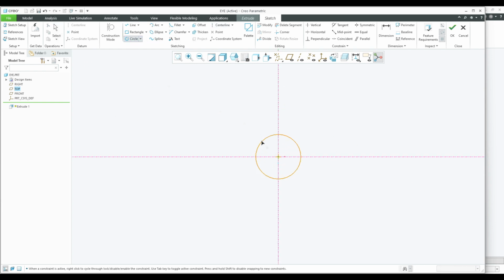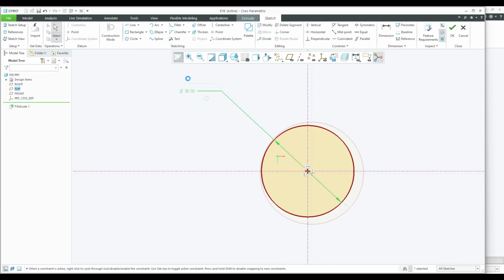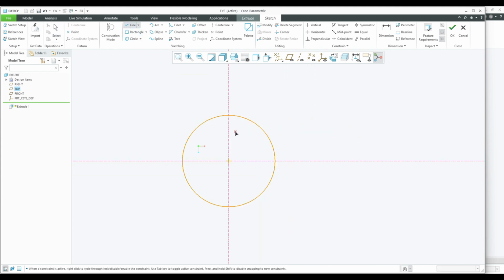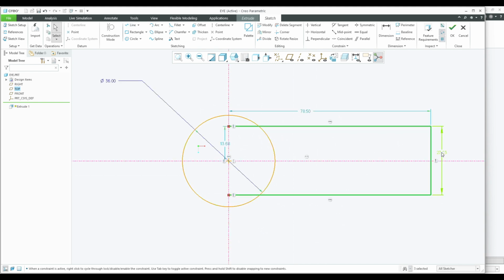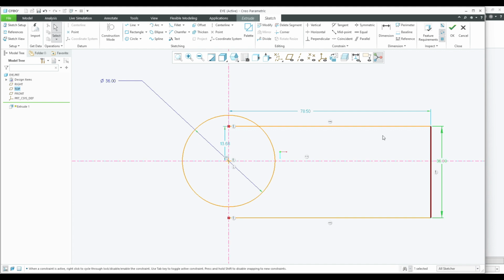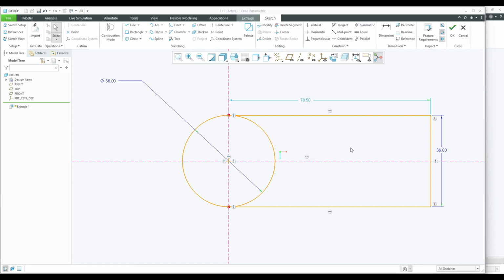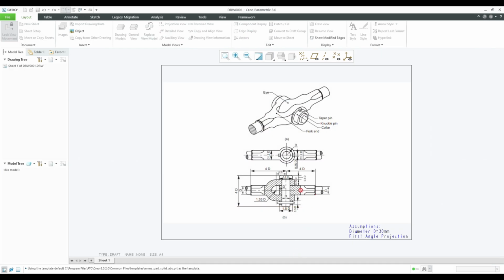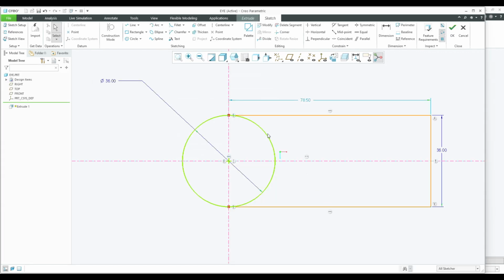So now I'm going to create a circle with a diameter of 1.2 into d, which is 36. That's great. Now I'm going to create another square structure like this, where this particular dimension is also equal to 1.2 into d, which is 36. So this comes in the direct value, and the length of this eye rod is also equal to 4 into d. So it is also 4 into d. We need no change, so it will be direct, no issues. And this particular hole I'm going to consider as 2d,